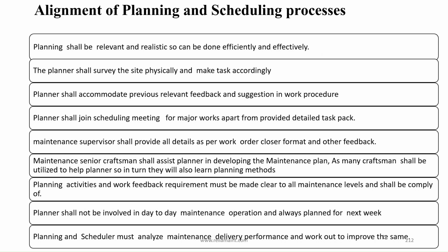Maintenance senior craftsmen shall assist the planner in developing the maintenance plan. As many craftsmen as possible shall be utilized to help the planner, so in turn they will also learn planning methods. Planning activities and work feedback requirements must be made clear to all maintenance levels and shall be complied with. Planner shall not be involved in day-to-day maintenance operation and always plan for next week. Planner and scheduler must analyze maintenance delivery performance and work out how to improve the same.